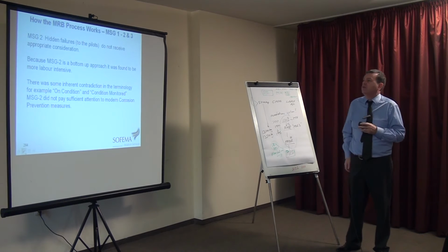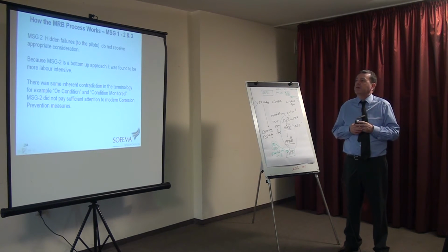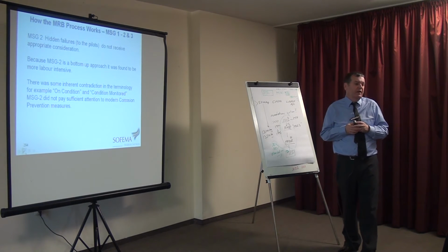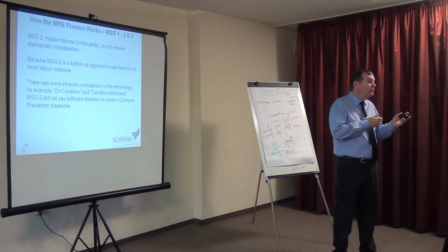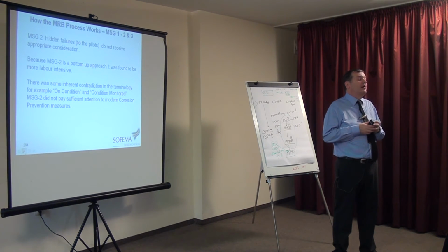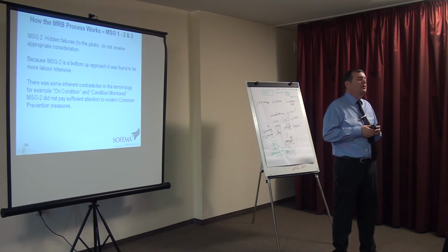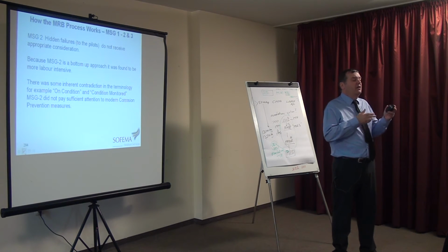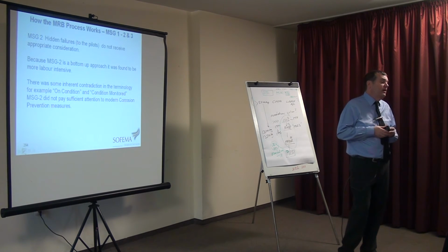MSG2 hidden failures to the pilot do not receive appropriate consideration. What do we mean by hidden failures? Well, we spoke about latent failures, where something is not working, but we don't know about it. The pilot is not aware that the backup system is not working. And the MSG philosophy did not pay enough attention to this.